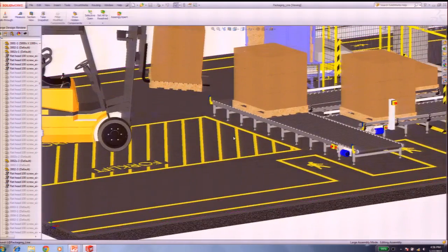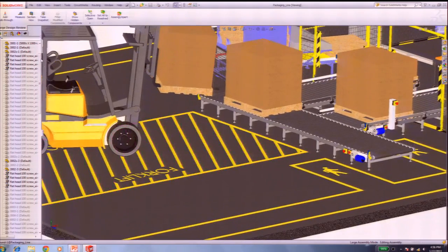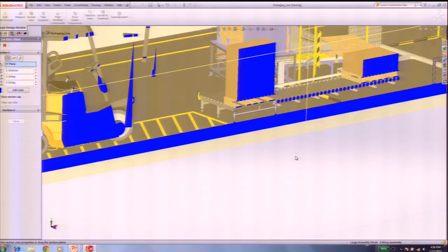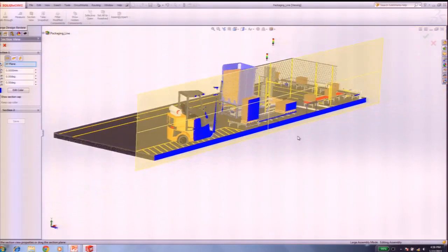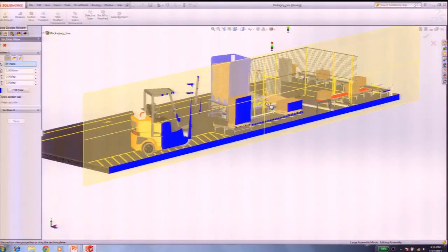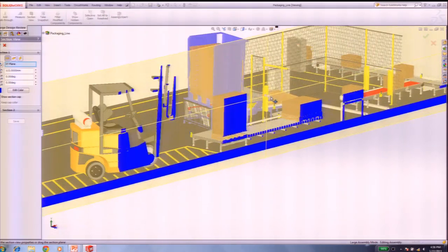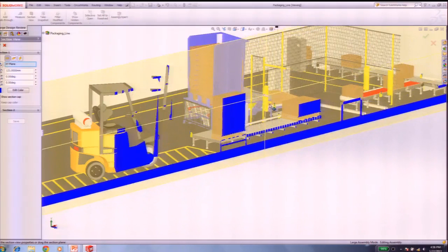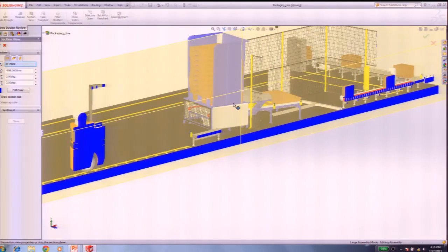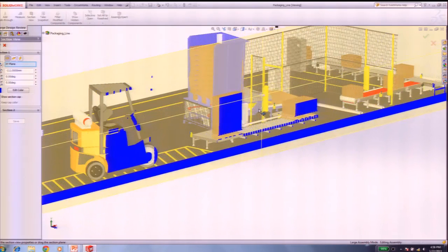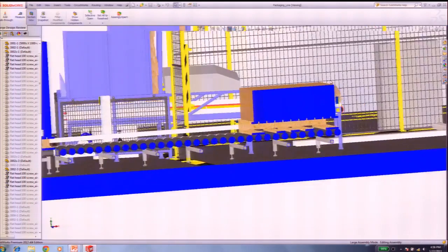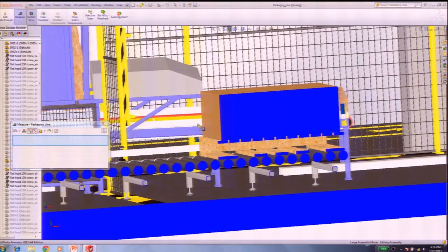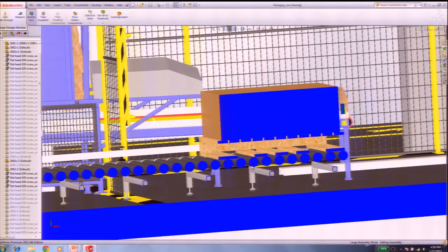Then, carrying it a little bit further forward, I can just insert a section. And here I've got my sections that I'm very familiar with, because it's just like standard SolidWorks design mode. Here I can drag my sections to go through and check out particular areas. Here, just simply accept a section, and then I can go in and repeat the process, measuring things, for example. Here, measuring in the section mode.